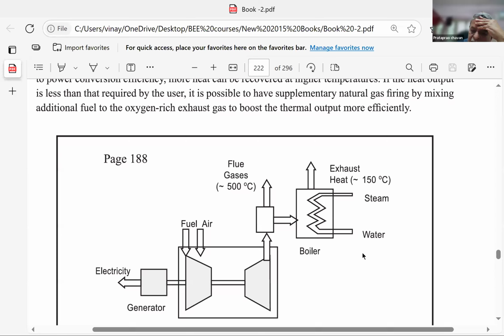and that heat is converting water to steam, which otherwise in a normal boiler what do we do? We put in fuel, burn the fuel, create a furnace, and the fuel generates the heat for converting water into steam. Here the fuel component is saved because you have ready-made high temperature gases. So here the gases will convert water into steam, and the gas temperature will cool down, of course, because they have imparted the heat to the water.